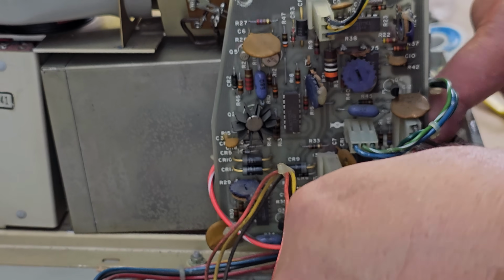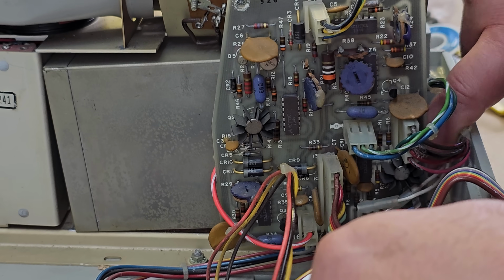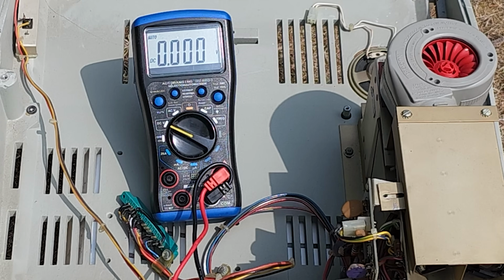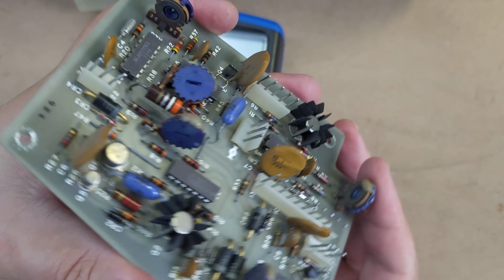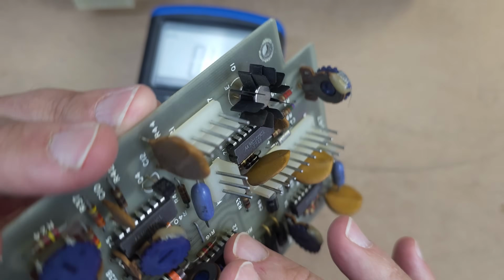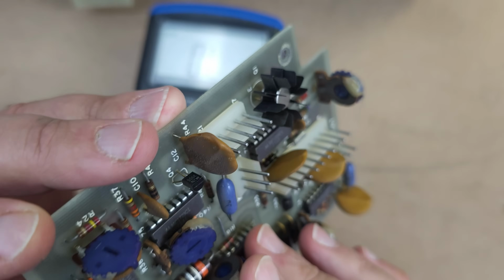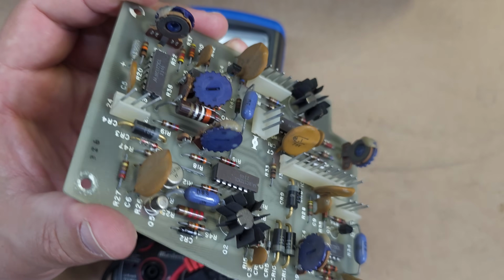Back to the power supply, I discovered one of the voltage adjustment potentiometers had some cold solder joints, so I fixed that up. And then back to the testing range to see what results we get. Slightly better, but I still have some weird or wrong or missing voltages, like minus 2.5. Yeah, I'm thinking that's not likely right. So I decide to pull the little board that I think fine-tunes the output, and that's when I discover a couple of potentiometers that are actually broken. So that might explain why I have low or no voltage at all at certain pins.